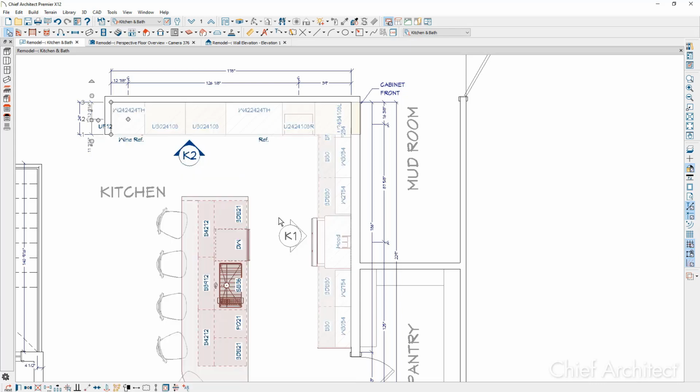And then just like in the wall elevation, you can clean up these dimensions and remove and adjust them as you may see fit. In this case, I may not want a side wall center elevation, and you can adjust these dimensions and move them around. This is a great starting point to have the dimensions. Many times I do like to pull these center lines into the object. Notice that I didn't get one for the refrigerator.